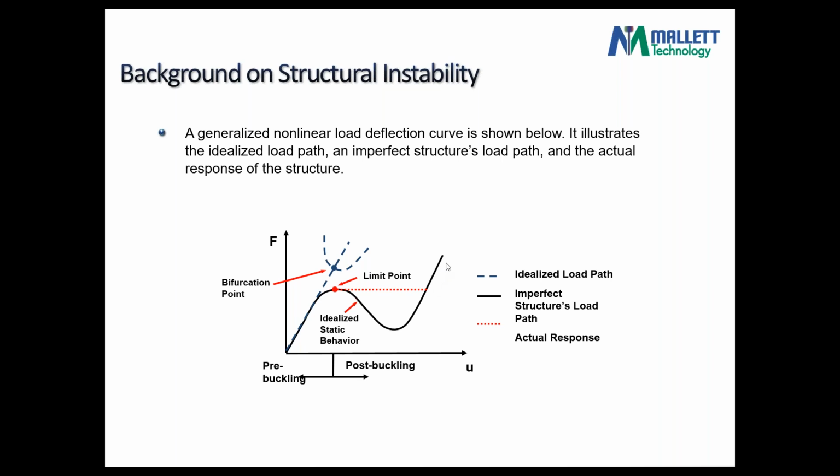However, if you really load it and monitor load deflection, what you will see is you climb on this curve and then you snap possibly to a different position because the structure will take another shape, from one shape to another shape. Now, we refer to this point as the limit load, a term which is used in engineering. This portion is very challenging for modeling. You can't ride on this. It will be very difficult. Some modeling techniques allow you to ride on that, but that's kind of tricky.